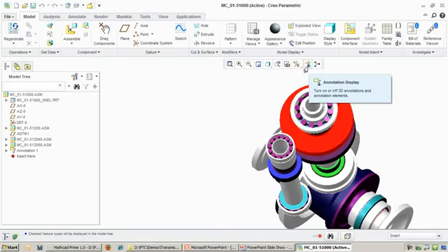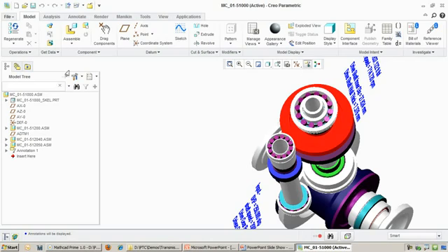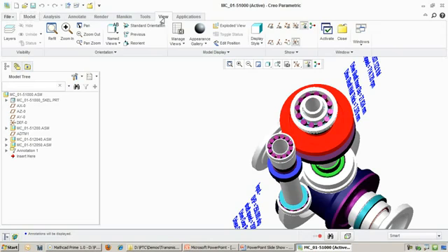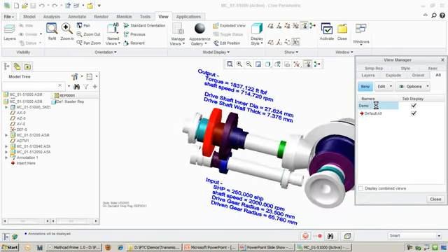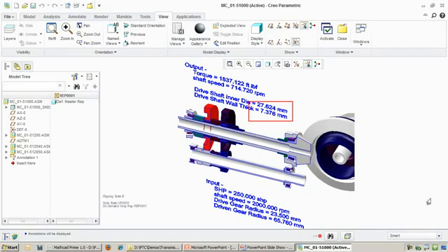We can put up some annotations to see the measurements we are dealing with. What you cannot currently see is that the input and output shafts are hollow. Let's use a cutaway view to look at the cross-section of the shafts along the length. The input shaft currently has a wall thickness of 7 millimeters and change. You might ask yourself, how was this number generated?